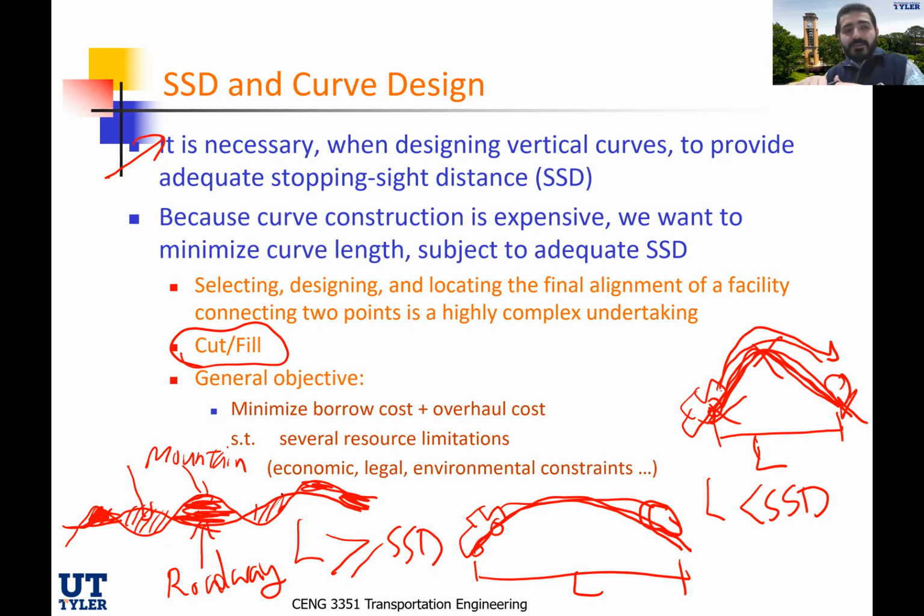the cut and fills? You would like not to have too much cuts because that's going to be a lot of money to cut through the mountains all over. And you would not like also to have lots of fills because otherwise now you would be required to buy good materials from elsewhere, haul it to your location, and compact it before you start paving. And that's also expensive. So you need to really manage between the cuts and fills to have minimal cuts or minimal fills, or at least minimal. The balance has to be there. Otherwise, it's going to be a costly undertaking.